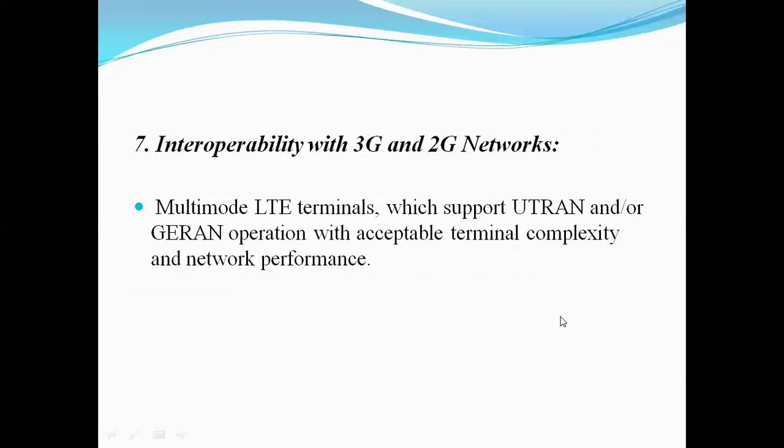The seventh one is interoperability with 3G and 2G networks. Multi-mode long-term evolution terminals with support for UTRAN or GERAN operation should be able to support measurement of and handover from and to both 3GPP UTRAN and 3GPP GERAN systems with acceptable terminal complexity and network performance.